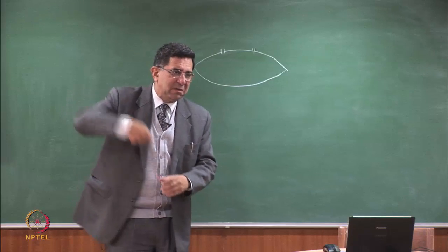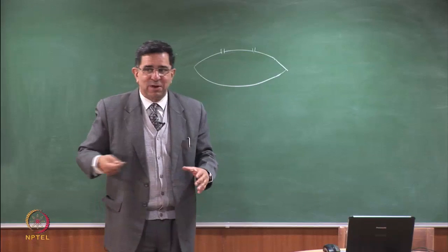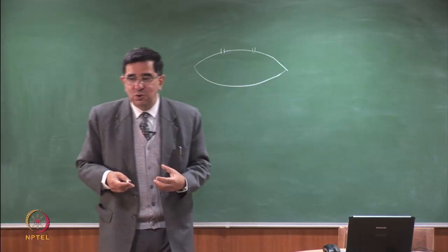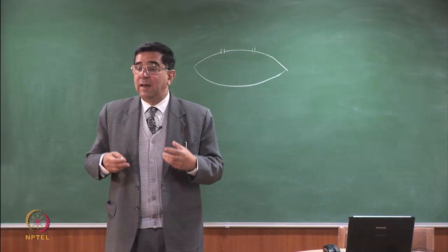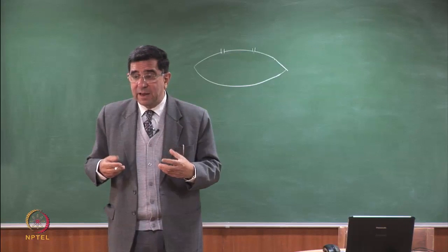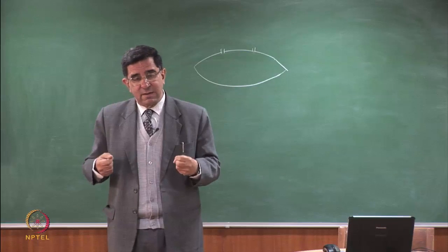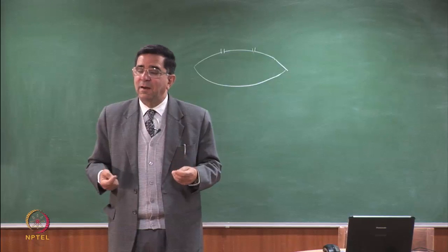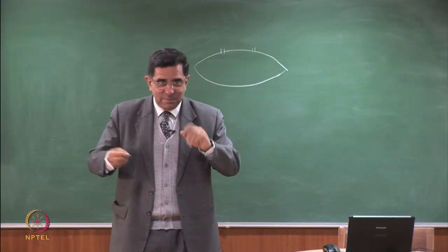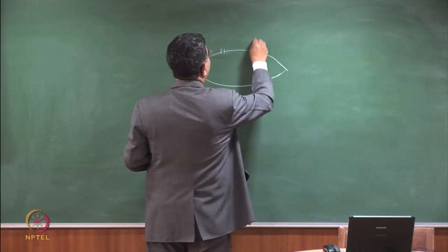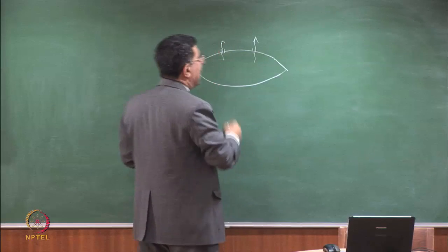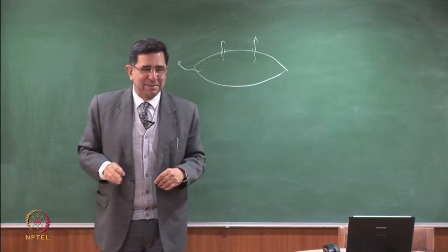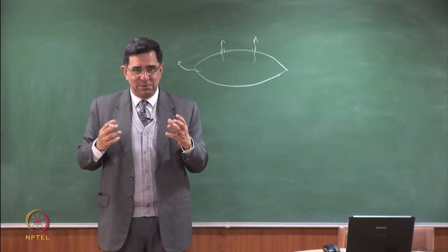But if I take a suction pump and start applying suction in those vents, I will take out more gas, that becomes an active system. So an active system is one in which you actively use energy, like a blower or a suction pump, to take out the gas. A passive system is one in which you take whatever comes out. That means gas will come out from here. This is a passive system. But gas may also be coming out from some leak. It will also be going somewhere else. Because there is positive pressure, only then does the gas come out.